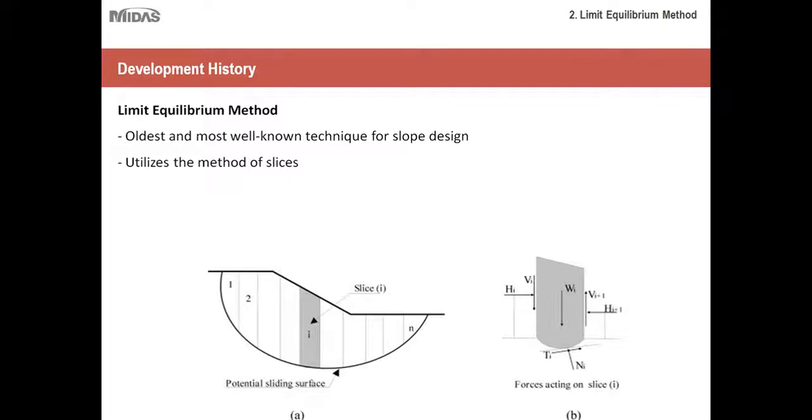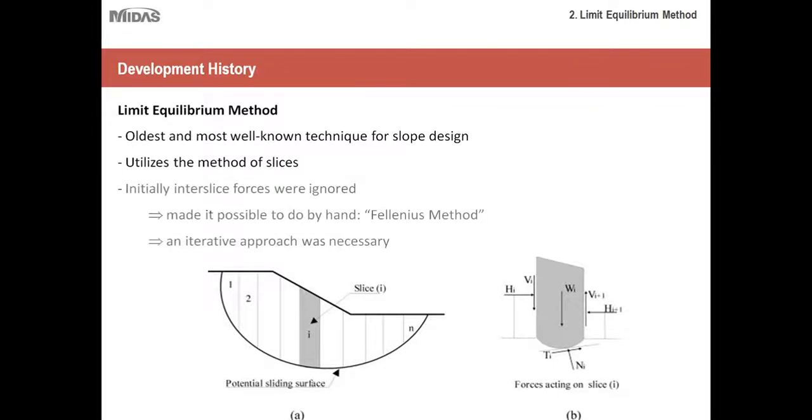But if you remember the picture that I first showed you, slopes typically tend to fail with this sort of curved failure surface. So you'll create that arc failure surface, and then you'll divide your slope into a series of slices, and then just using the laws of statics, you'll find all of the forces acting on those slices, and then using those forces you can determine the factor of safety or the stability of it, and we'll talk more in detail about it in just a minute.